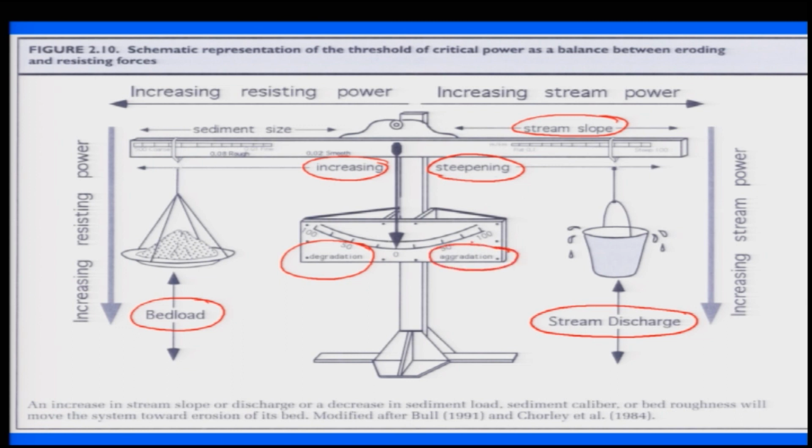Okay. Now with this, let's see how different terraces can be classified, where we can term these terraces either as aggradational terraces or degradational terraces. As we discussed, if the terraces are formed cutting its own deposits, then we term that an aggradational terrace, and if the terraces are formed cutting the bedrock, then we term that a degradational terrace,